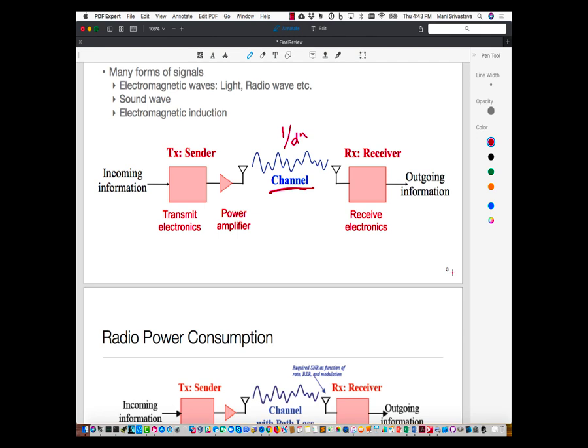We, by the way, saw the same thing in processors also. If you recall, very early on in the course, I had given these examples of big.LITTLE, right? The big processor, tiny processor, and the big processors were actually much more efficient in terms of energy per unit work done. It's just that that efficiency would manifest when we could keep them satisfied, right? I mean, if I had a big workload. That's the tension which plays out, and we see pretty much the same thing in radios.